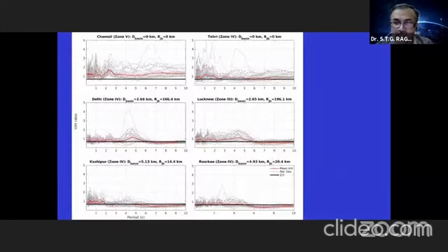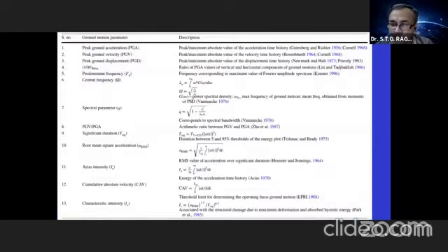And not only this, we have also done some numerical simulations for large magnitude earthquakes. We have also observed that these V by H ratios are extremely on the higher side, not 2 by 3, and they are functions of time period, and they will vary; they are more than 2 by 3. And now, as Professor CVR mentioned, in the code you will find PGA, PGV, PGD only. But now there are some more extra parameters which indicate the damage. Generally PGA is not highly correlated with the damages. So there are other things like energy-based design, which he mentioned also.